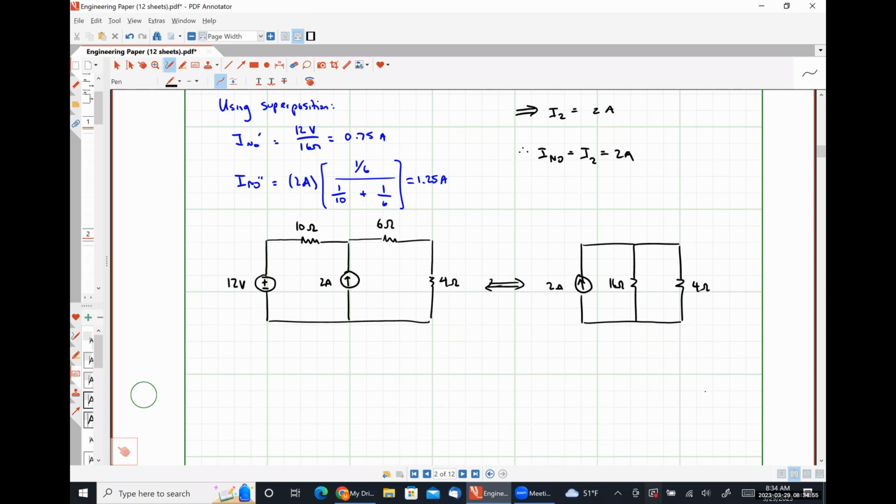So we can say pretty easily here that V Thevenin is simply equal to I Norton times R Thevenin, or we can say that I Norton is equal to V Thevenin over R Thevenin, or we can say that R Thevenin is simply the ratio of V Thevenin to I Norton, meaning technically speaking, we only need 2 of the 3 quantities to figure out what the third one is.